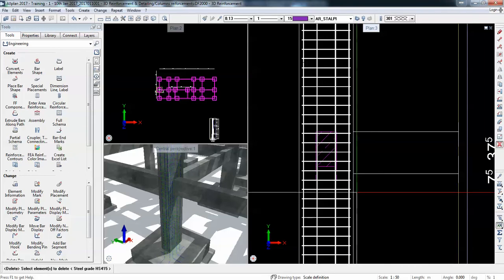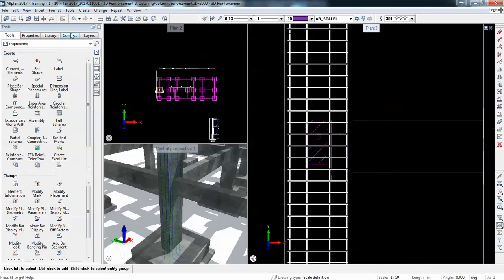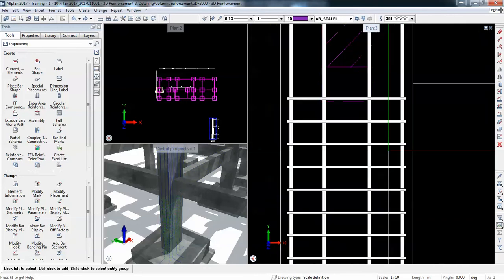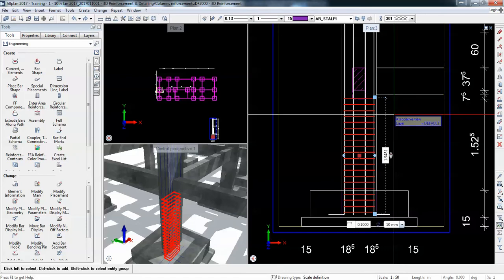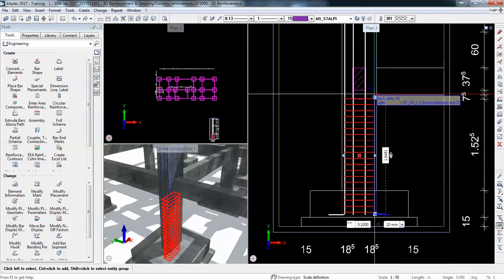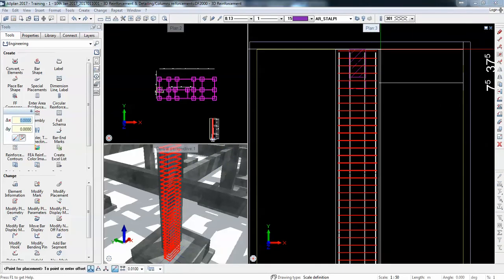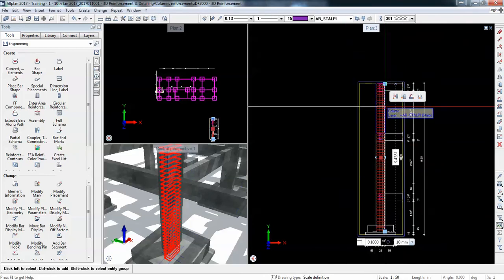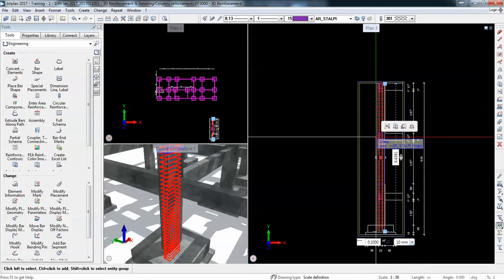How you have extended the stirrups throughout the length of the height of the column? How did I do that? Yeah, you have to hold the shift button and click on any stirrup. If you do this, you will see you have parameters for spacing, for changing diameter, and then I just pick up this handle and go upwards. So this is one placing. The moment you start changing steps for the placing, you will get separated placing areas.